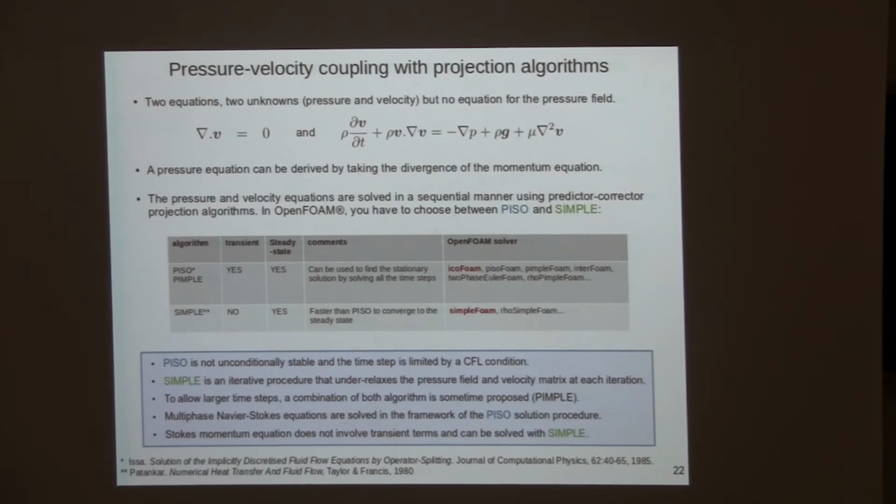There are some techniques that combine both PISO and SIMPLE. In OpenFOAM, they call it PIMPLE. The main idea is to do a transient simulation with a PISO algorithm, and in between two different time steps, they solve a SIMPLE algorithm to allow larger time steps. That's what was said initially.